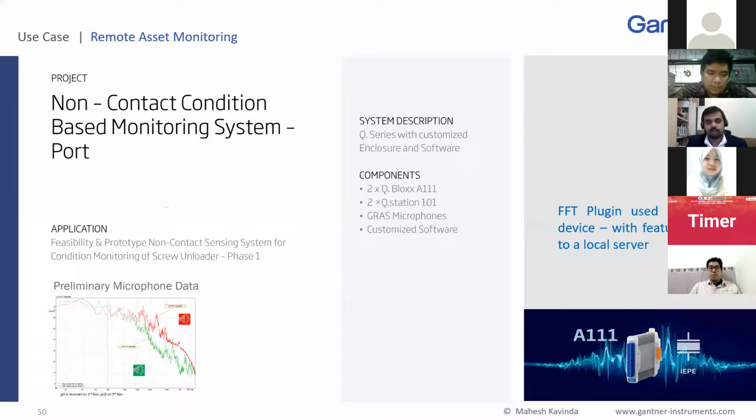We can't use the typical scissor lift and climb up, so we came up with a little mechanical structure next to the screw unloader, mounted all the microphones, ran a one IP signal, and kept the devices pushing data based on the trigger. Each and every event was recorded and pushed to our server, and from there we started analyzing. We collected the entire raw data and the event-based, triggered data.